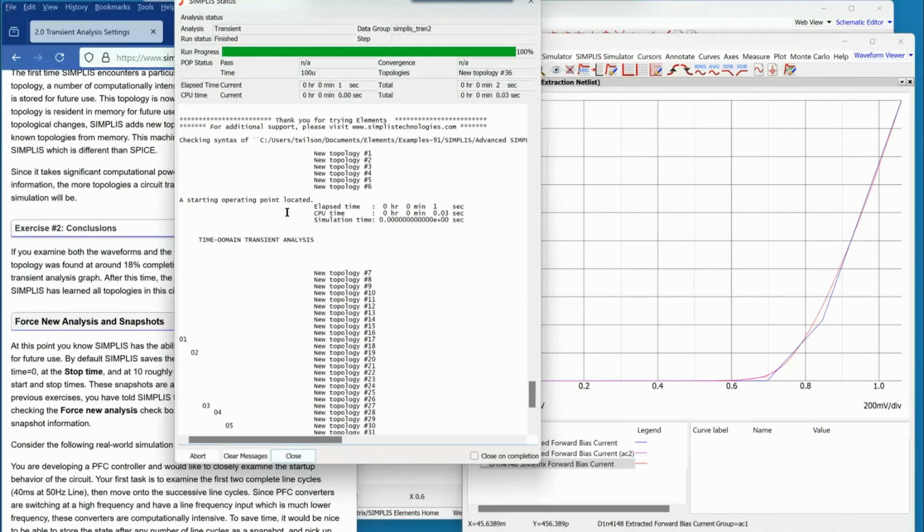But I may not want anyone else using it. I might have made it for a specific reason, that I may only be modeling a few things, and I might be making the diode unusable for other applications. It's like an ideal part, for example, or I may have modified something else that's not realistic. That's why I'm saying if you give it a unique name, then you're not going to accidentally use it, and nobody else is going to have it unless you give it to them. Okay, so that's the way to do it. I think so. Yes.